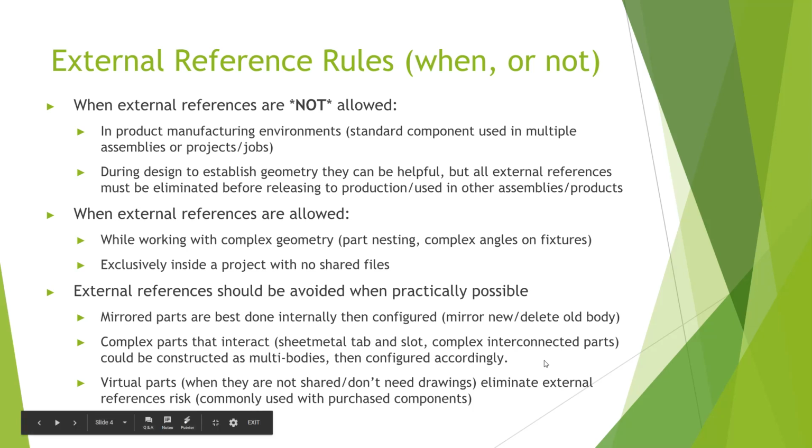But complex parts that interact. I've got a couple of really good examples coming up, but if you have 3 or 4 parts that are very complex, that all interact together, that have to geometrically fit in a particular way, using external references can often be to your detriment.